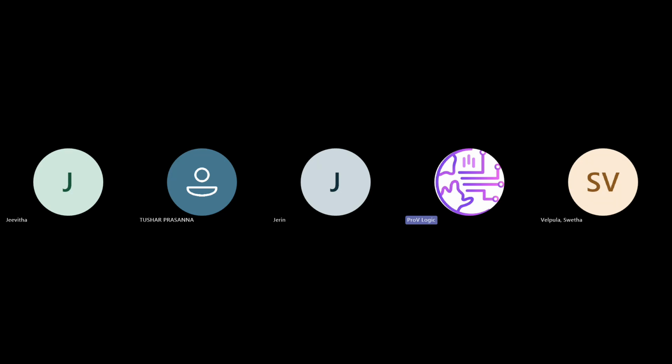What is meant by a bad latch? How are bad latches inferred in Verilog, and how can we avoid them? Jerin, can you answer? Bad latch is a condition where, when we are defining multiple branches in a statement, some of the branches are not defined.